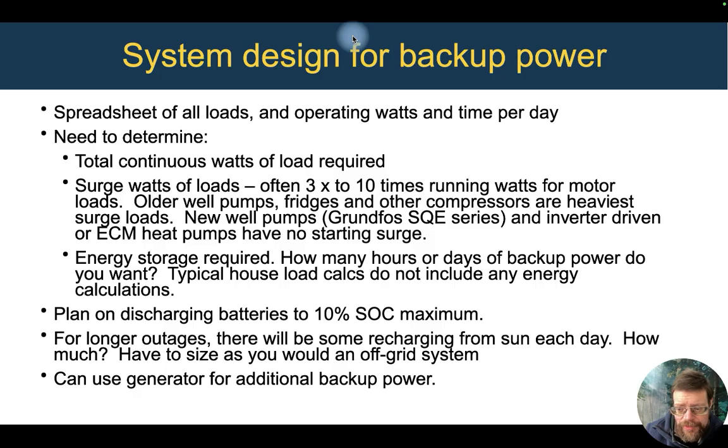Typical electrical load calcs when sizing the panels on houses are all about power. What's our peak power coming through? Do we have enough amperage? Do we need a bigger load panel to handle that peak power for the house? They're not really concerned about how long that is occurring. Does that peak power occur for 30 minutes or 22 hours a day? That's a massive difference in the energy use, with no difference in the sizing of the equipment as far as amperage of the main electrical panel.